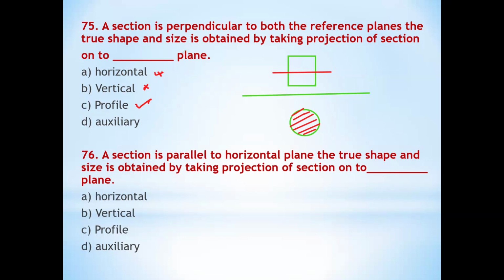In another way, they can ask it by saying the section plane is perpendicular to both the reference planes. If the section plane remains perpendicular to both the reference planes, that means it is parallel to the profile plane. We have to remember that. So here, option C is the correct answer. Now, next.